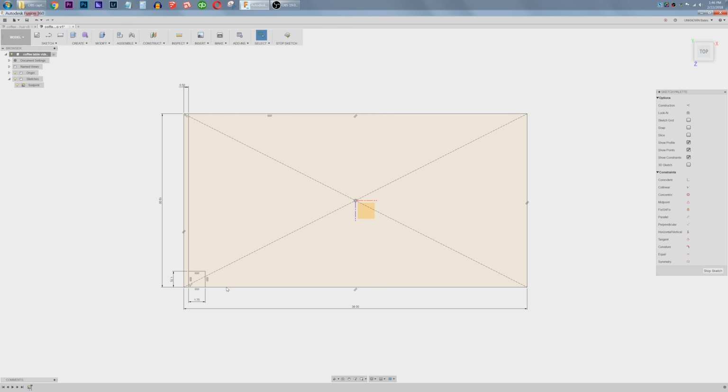So in this case, I'm going to mirror this leg over to this side and then mirror both of them up to here. And I need a mirror line. So if I go R for rectangle and draw a 2-point rectangle from the center of a center point rectangle to the outside corner of that, it gives me 2 midlines. Now before I click, I'm going to change that to construction so it doesn't change my overall profile there.